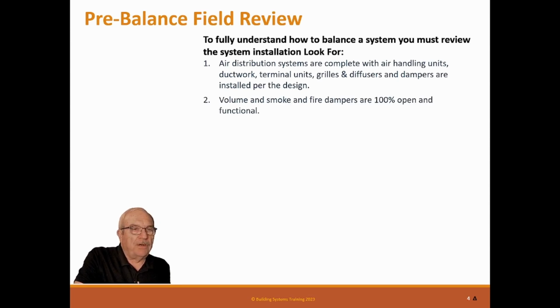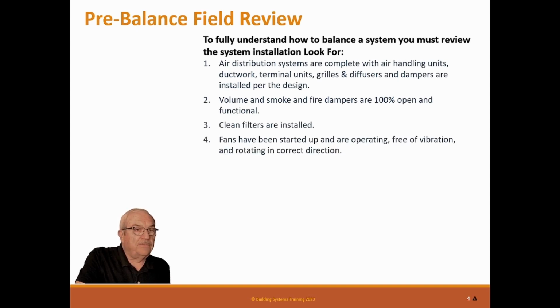Volume and smoke and fire dampers are 100% open. Remember, everything has to be 100% open for us to balance. Clean filters are installed. Fans have been started up and are operating, free of vibration and rotating in the right direction. If a fan is vibrating badly, then operating it will damage it. So you don't want to do that.